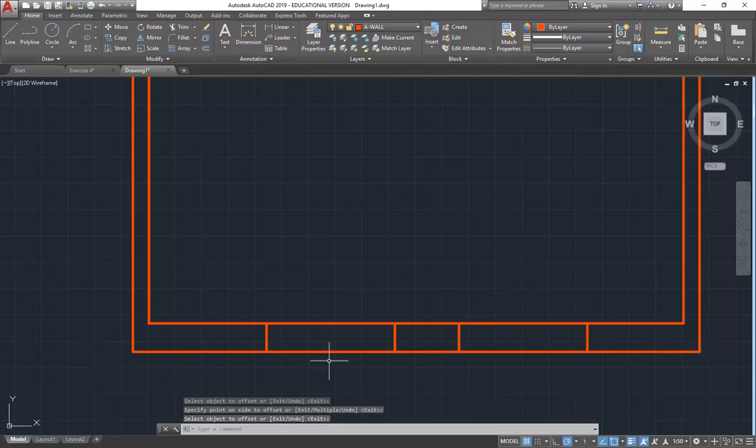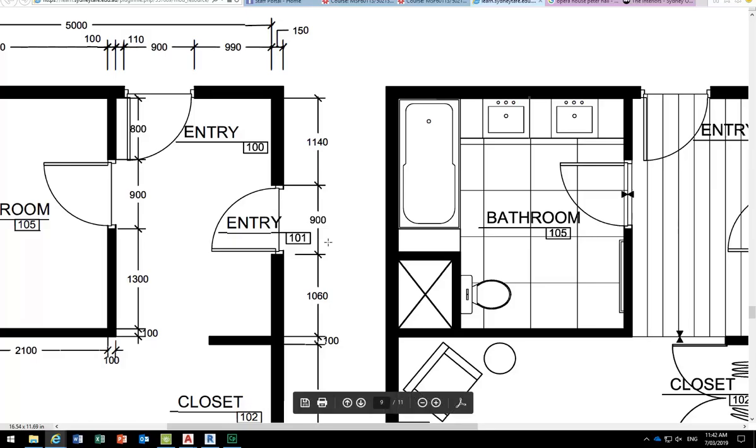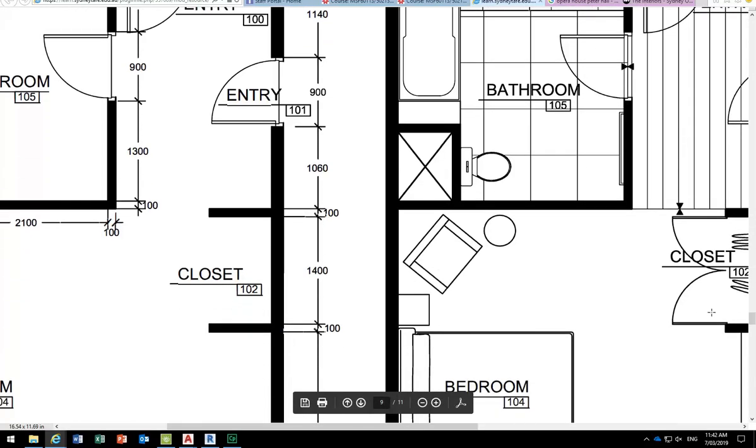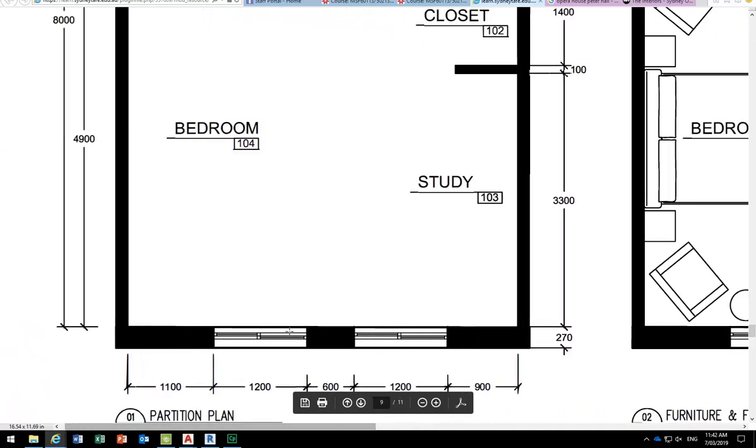And now I'm going to do one extra thing that hasn't been done in these drawings, which I think is not very good, because I've been talking to you a lot about line weights, and that's one of the most important things, to get your drawings right in terms of the conventions. These heavy lines make it, I think, well, it's wrong, but it's also harder to read because those lines should be light to show that it's below the cut plane. So it's really, I think, just not good. I can't think of a better way of saying, but it's really not following the convention, but also, to me, it just reads really badly.